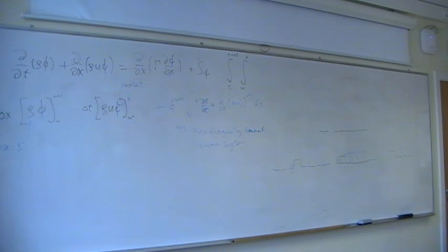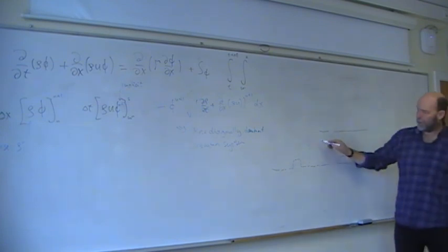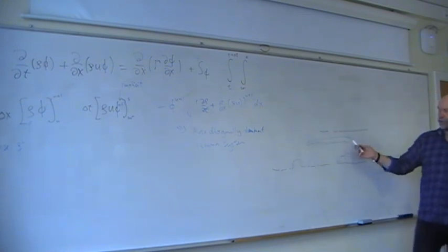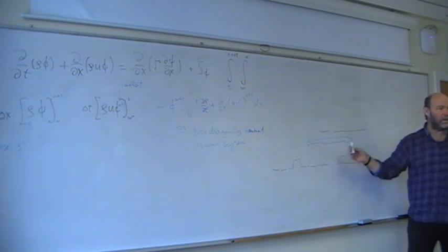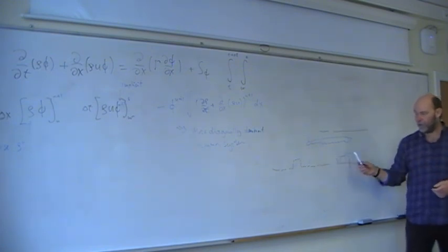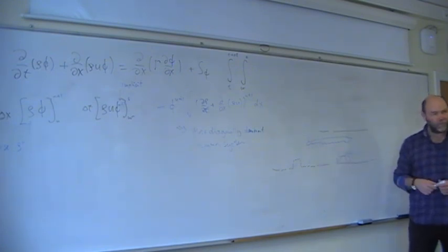Because if you have a long turbulent structure of some kind that spans your entire domain, you just feed it unphysically, you send it in again. And that's not correct. So your domain has to be big enough in order to do this.